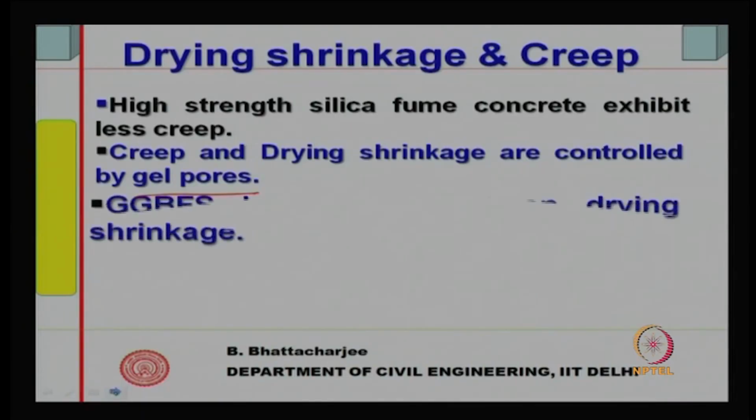So, creep and drying shrinkage both are controlled by gel pores and gel water. So, if gel water can be held for a longer period of time, the drying effect will be much less, and shrinkage also, and the creep effect will also be less.